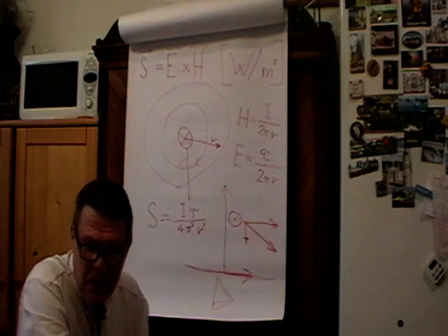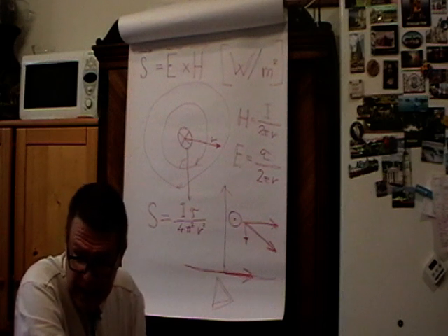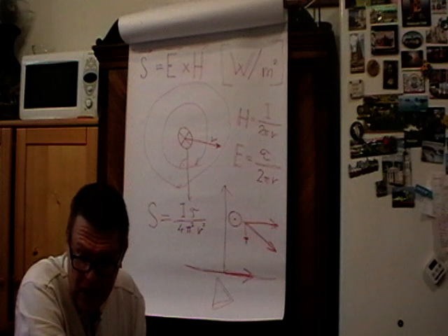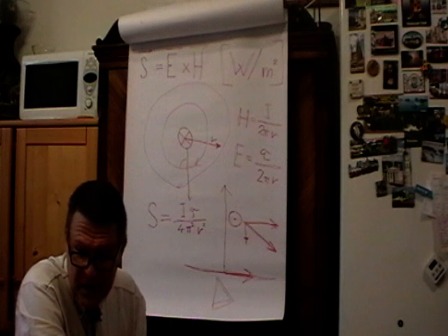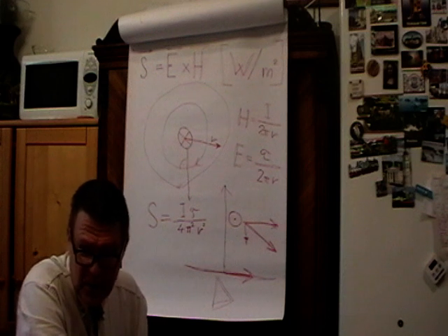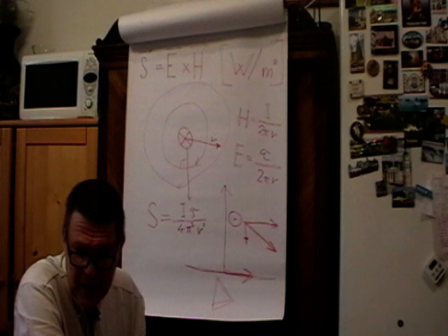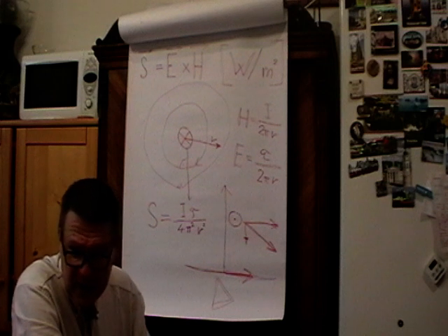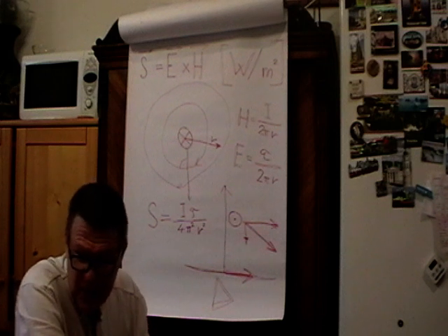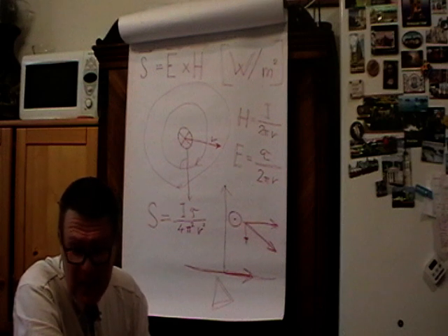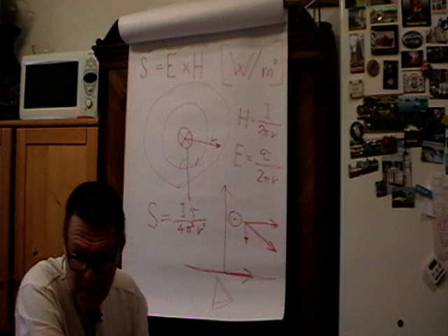So the result of that is electric heat. We have a conductor that becomes hot. For outer transmission lines, we can get up to 10 amperes per millimeter square. That's a good rule, which will make the conductors warm but not melting.